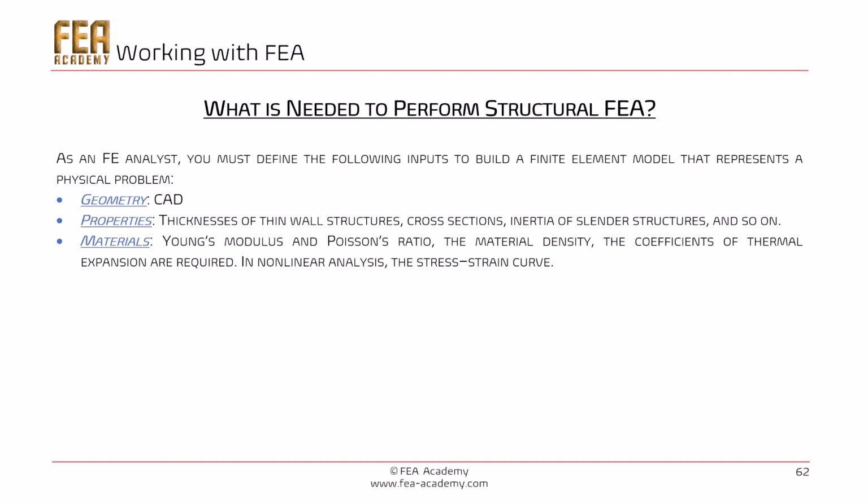Also, for the composite analysis, you will need to know the material properties of the plies, but also information about the stack-up, the orientation of the plies, the thickness of the plies, the number of plies involved in the composite structure.